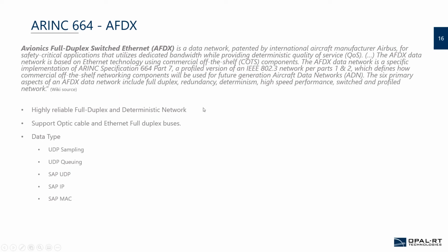It's really to bring a full duplex environment, not like the two-wire buses that is the ARINC 429. Now we have full duplex buses here. What is neat is you can have Ethernet wiring connections, and they also support fiber optics if required.